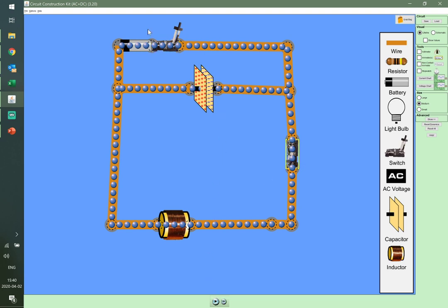So I'm going to close the switch and open that switch. So now we just have a capacitor that has some charge in the circuit with an inductor that is not energized at all because the current was 0. So as it begins, you're going to see that the electrons, because of the charged plate, would want to go clockwise.